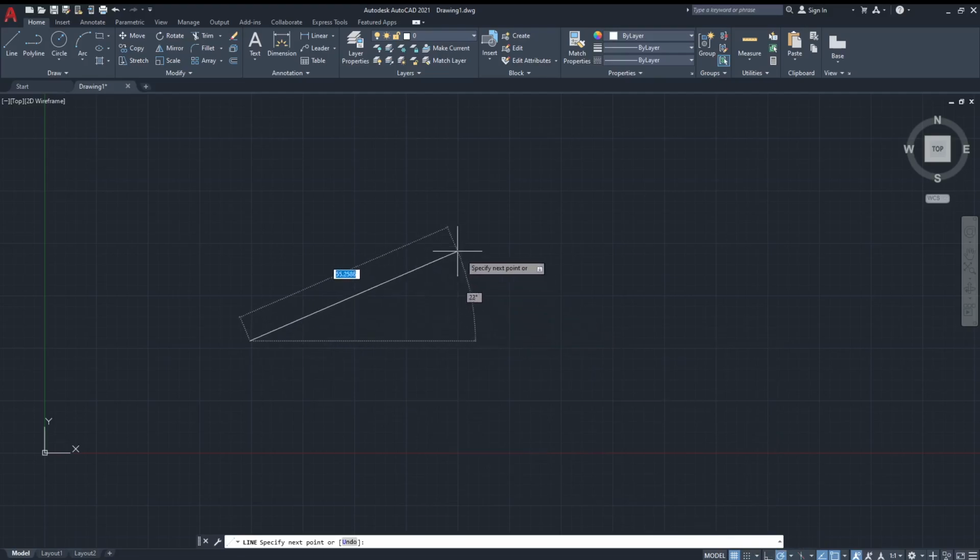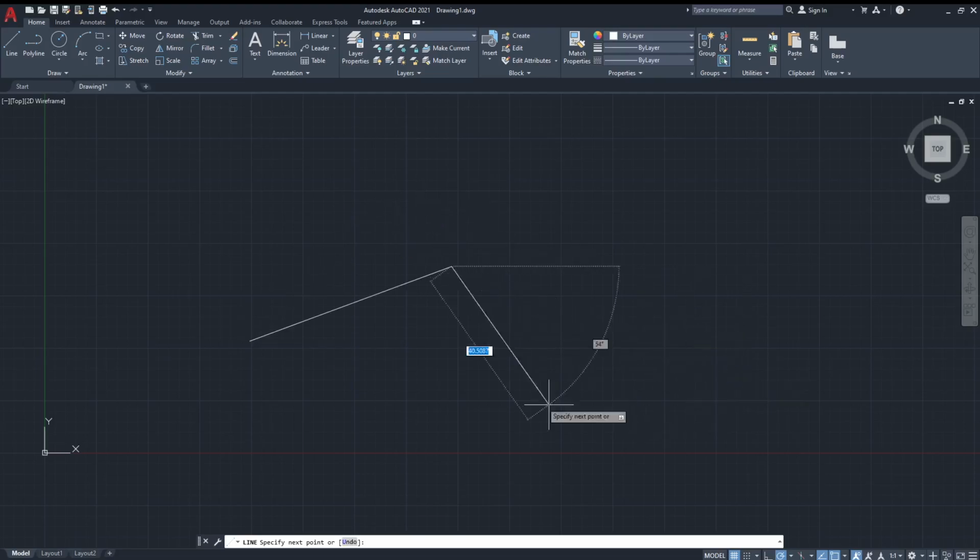But just make sure you have this one on for this particular case. As you can see here, right below my cursor, you can see an angle, a degree. If I press Tab, look, the blue thing is now choosing the angle. So if I write 20, here you go, I've written 20. So I go back and I choose the length. I go 13, I go Tab again.